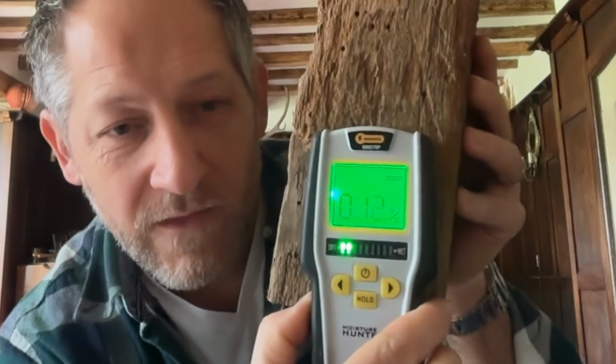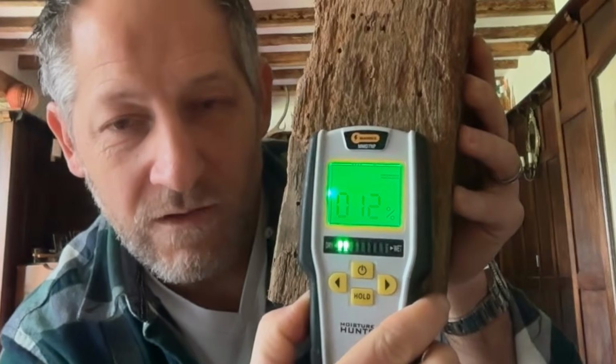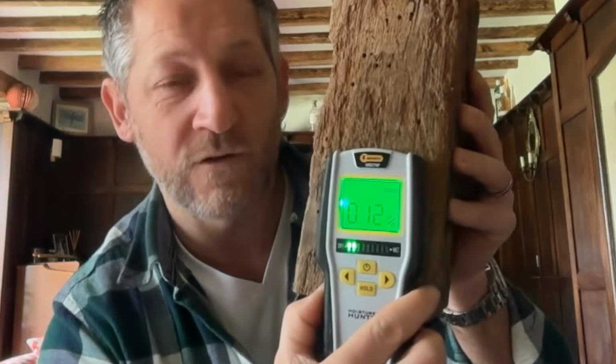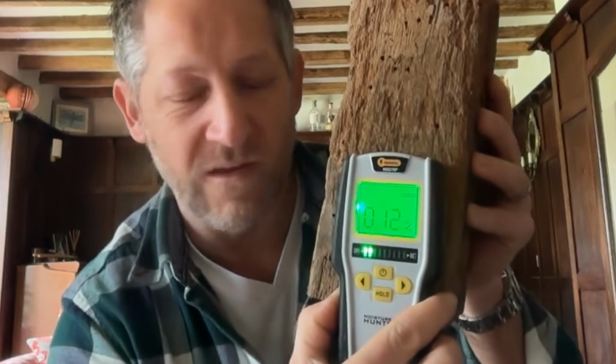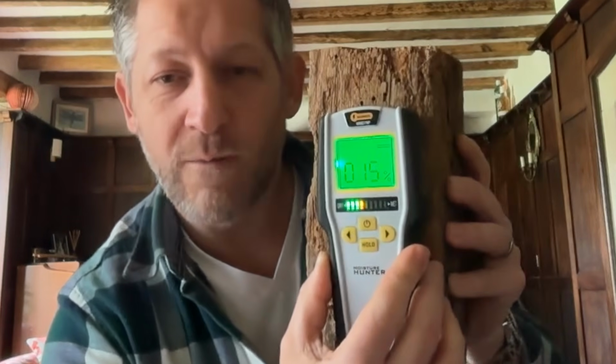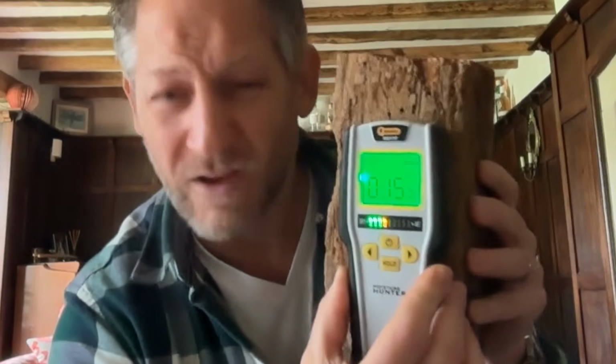But if I just stick this capacitance meter up against here, and hopefully you can see that for the YouTube viewers, see that's saying it's got 15% moisture in this. Now, the way this is working, this is actually sending out a small radio frequency to the first couple of millimeters of thickness of the timber. It doesn't penetrate very far. And what that's basically doing is measuring how much it bounces back. And by determining the resistance, if you like, of those radio frequencies returning back, a bit like a radar, I suppose, it's then determining for you what type of resistance in a timber, i.e. oak or hardwood like this, that you're going to get.